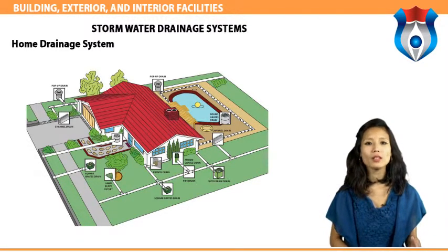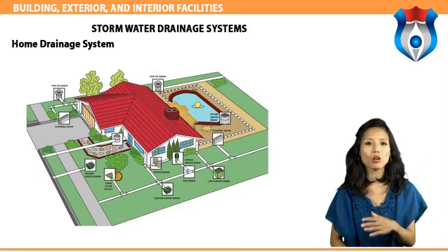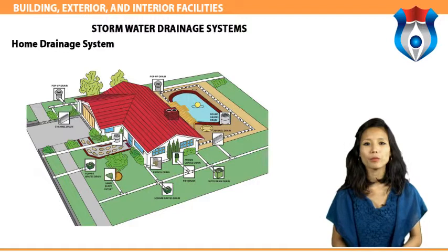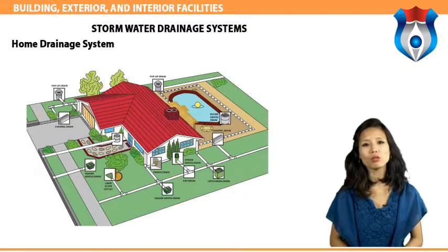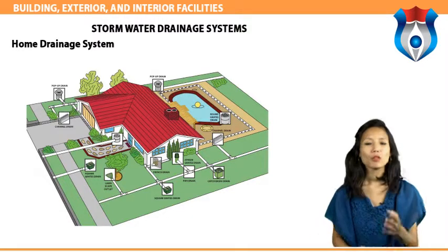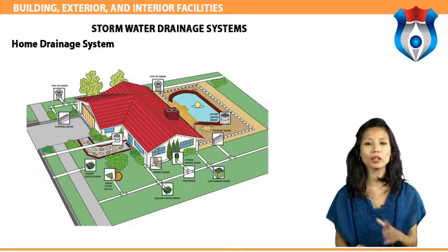The storm water service manages roof and surface water that comes from rainfall, snow melt or garden hose. Sloped lawns and driveways direct water from the roof and the ground to the street, where catch basins are located. Water that seeps through the ground is collected by a foundation drain located at the bottom of the home's foundation. The foundation drain may enter the sump pit where it drains by gravity to the storm sewer line, or may be pumped to the surface by a sump pump. Note that because of the improved drainage system, new houses do not have or need sump pits.